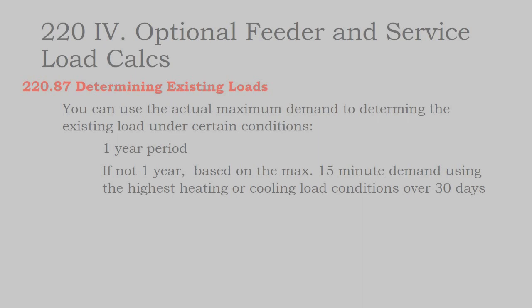And so before they go and review that, before that process comes in, you may actually want to go around and turn on all the circuits in your home at the hottest time of the day for a 30-minute window under a residential service, just so that you can spike your load all the way up to its maximum, so that when the utility reviews your electric use, they can't come back and say, well, your load doesn't get anywhere above 16 kilowatts, so a 48 kilowatt array is way oversized for your use.